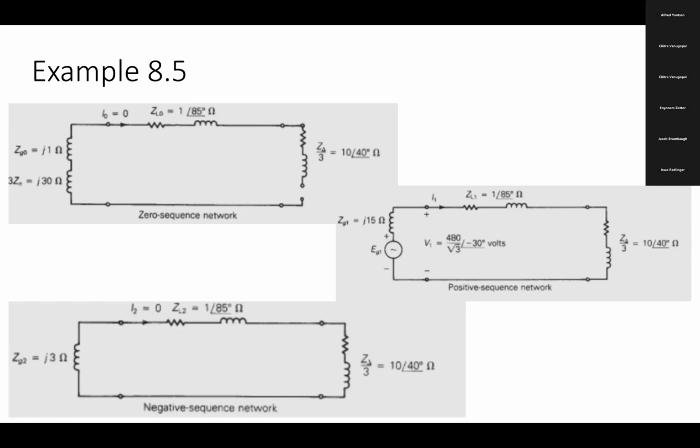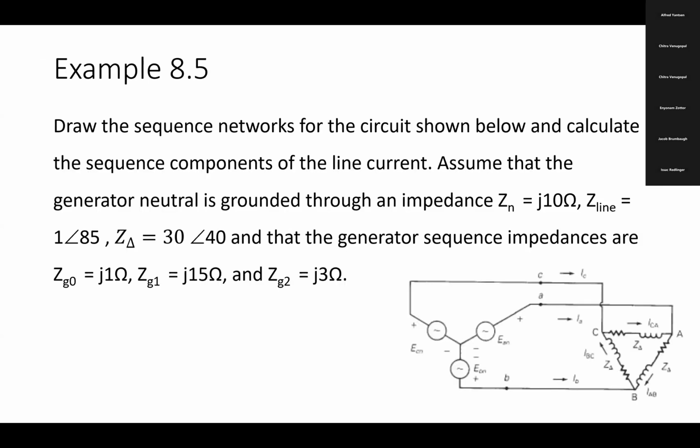Let's start from the positive sequence. For the source, how do you draw the source for the positive sequence? It should include the voltage source, and the impedance, whatever is given. It is connected in Y, so the impedance can be transferred as it is. If it is delta, then only the impedance should be divided by 3. But the source here is Y connected.